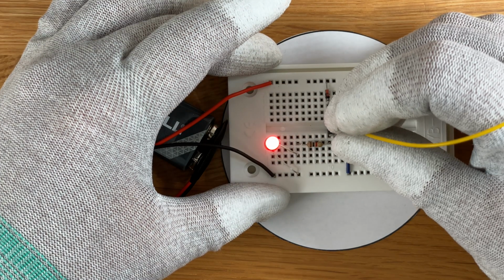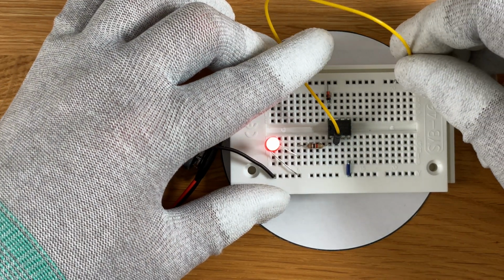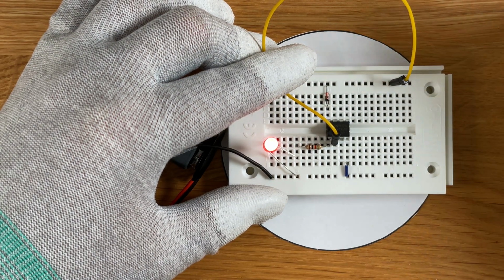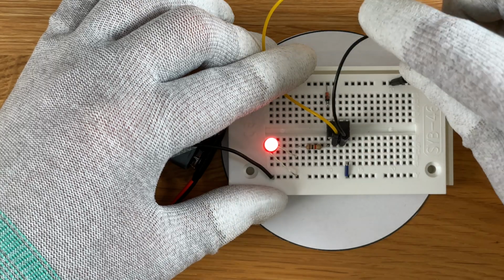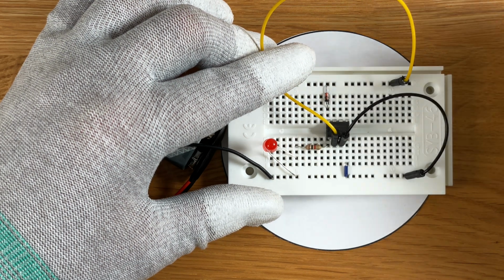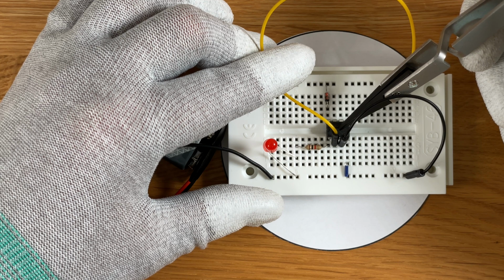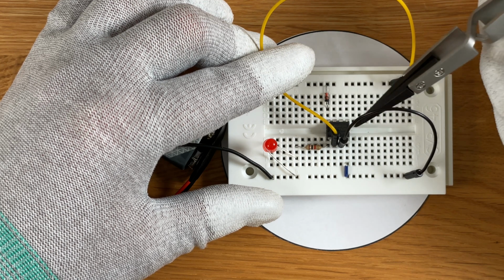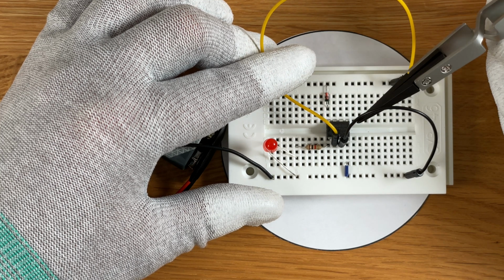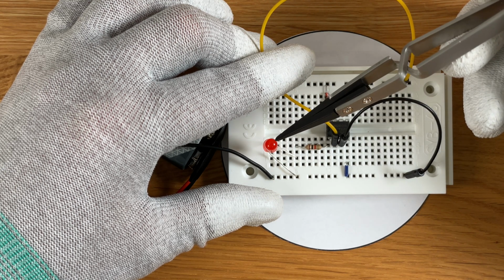And now let's connect the two inputs of the operational amplifier to actual voltages somewhere on the board. Let's connect, for example, the left one using a yellow cable to the plus 9 volt power supply, and the other one by using a black cable here, for example, to the negative terminal of the battery. As you can see, the light goes out, and the reason behind this is that the differential measured by the operational amplifier is now at minus 9 volts. We have connected these two connectors in such a way that the difference between input 1 and input 2 is negative, and this means the operational amplifier switches off its output, and this is why the LED goes out.